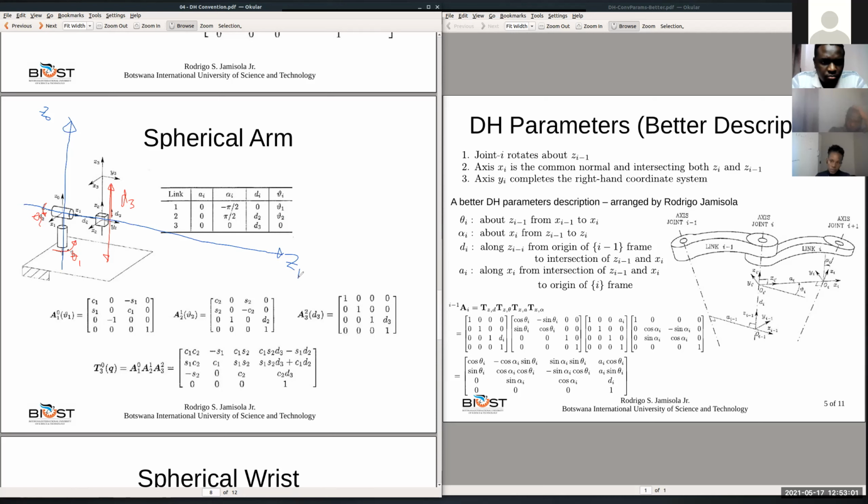What about this movement, the movement of D3? Well, in this case, it's not that joint i rotates about Zi. So Z will be along this axis also. This is where the axis of motion for D3 is. Again, the joint either rotates or translates. In this case, it doesn't rotate but translates. Joint 3 translates along Z2. So this is your Z2 axis.